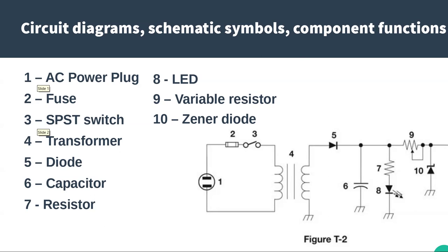We talked about that a little bit last week, where the diodes have a special property when they're reverse biased. At a certain voltage, they will conduct in the reverse direction, and that's called the Zener voltage. So they can be manufactured with a very specific Zener voltage and used as voltage reference sources.